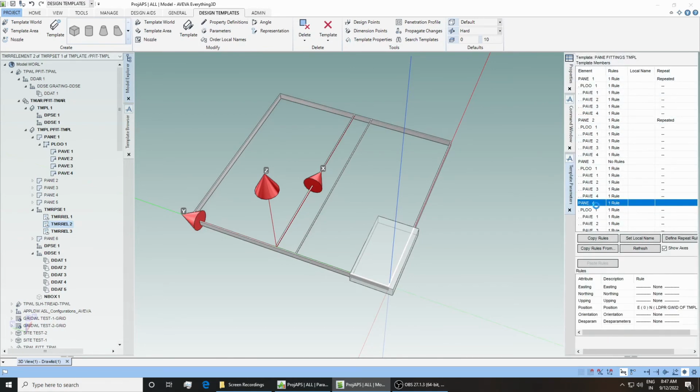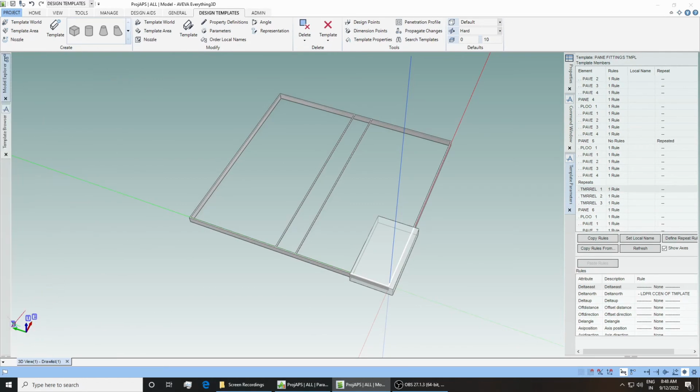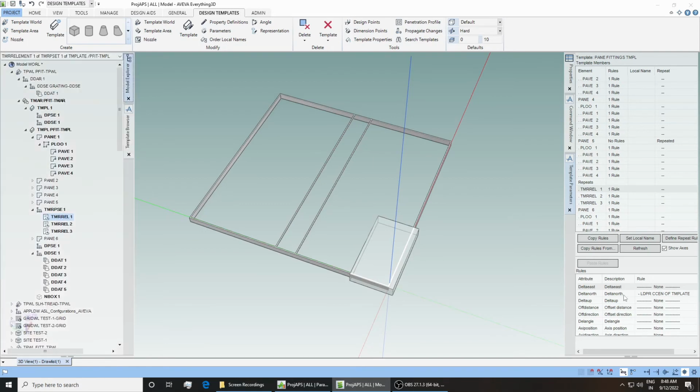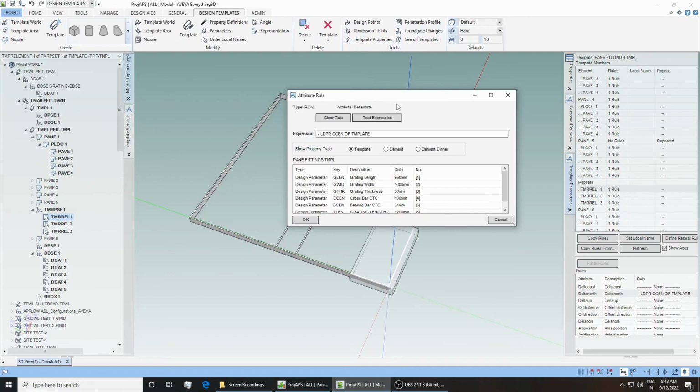As you can see, this is our repeat rule number 1. If I minimize this, you can see that this y direction is the north direction. Under this repeat rule, there is this delta north, so I have to give the delta north value. We have defined the repeat rule as 100, but I have to parametrize that 100 again by using our design parameters.